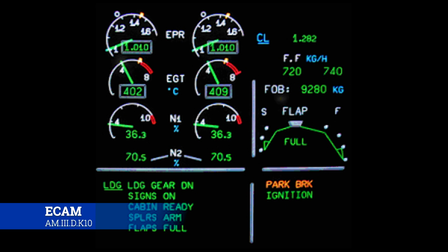Now this will lead you to what I call the Airbus reset, where you could have a 737 and an A320 side by side having the same issue. A lot of times with the 737, I can plug it up to ground power and run down through troubleshooting what the issue is. But with the Airbus, the longer it runs, the hotter it gets, the more crazy faults it'll throw. Next thing you know, you're just chasing gremlins in the system.